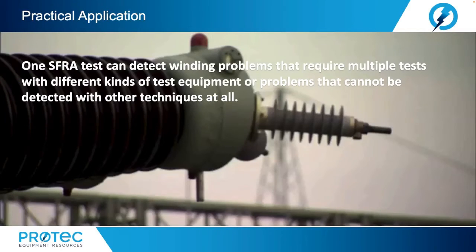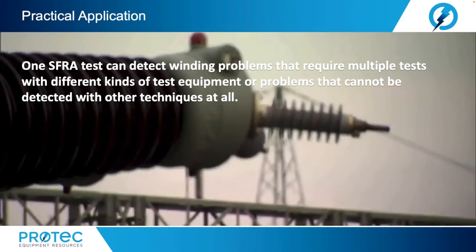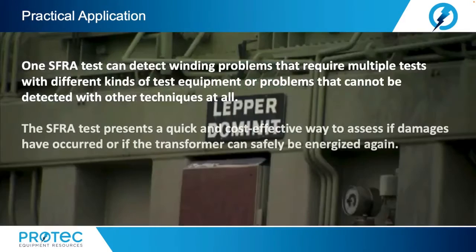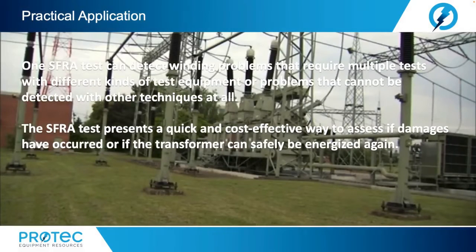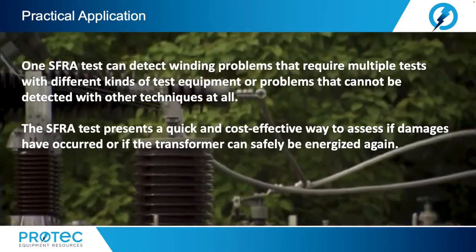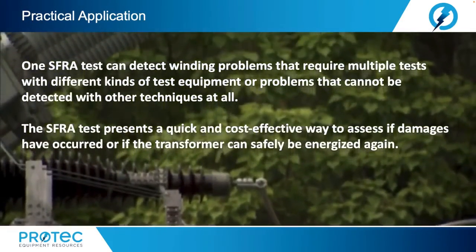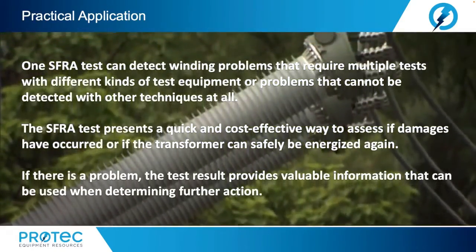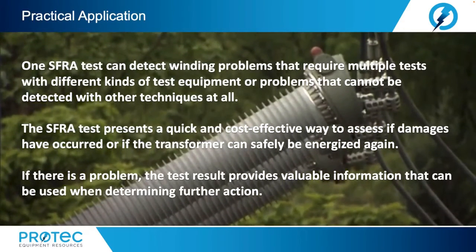One SFRA test can detect winding problems that require multiple tests with different kinds of test equipment, or problems that cannot be detected with other techniques at all. The SFRA test represents a quick and cost-effective way to assess if damages have occurred or if the transformer can safely be re-energized again. If there is a problem, the test result provides valuable information that can be used when determining further action.